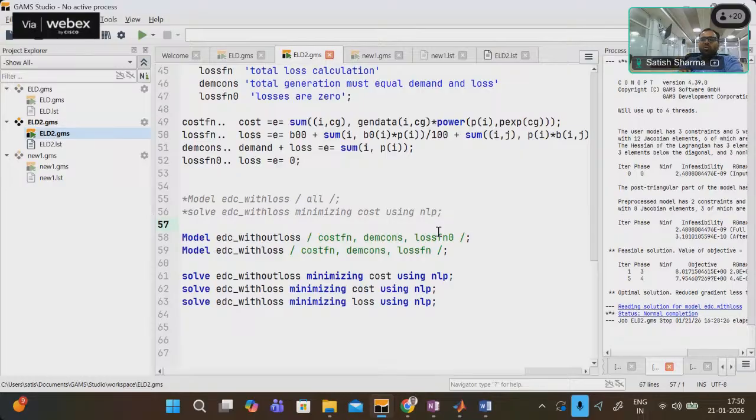Those are ramp limits, and sometimes, if you turn on a unit, you cannot turn it off the next hour. You have to keep it on for a certain minimum amount of time. All those integer-type attributes of that particular problem are solved in unit commitment.